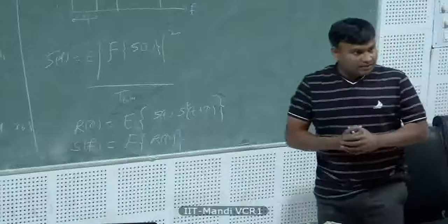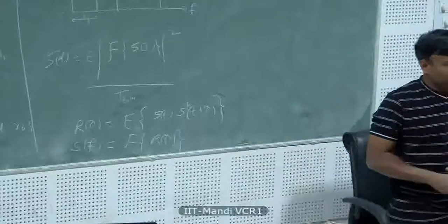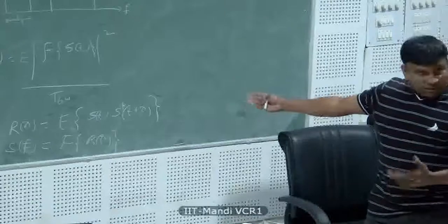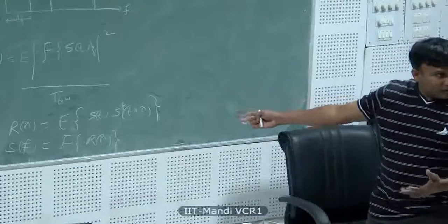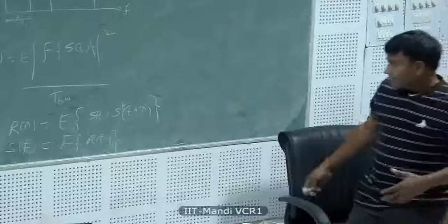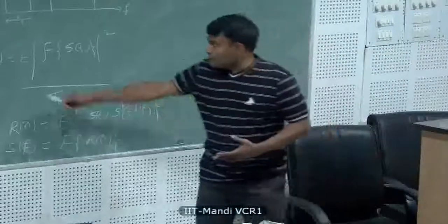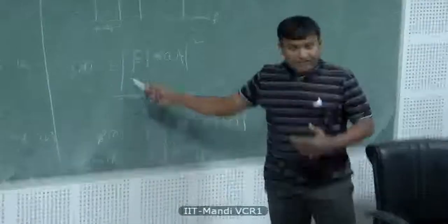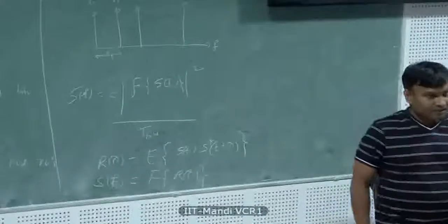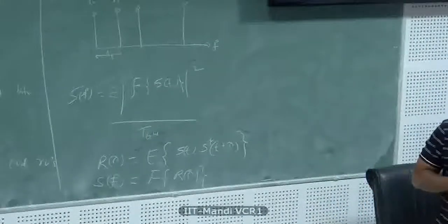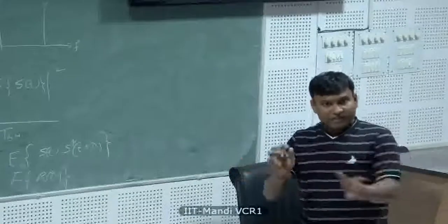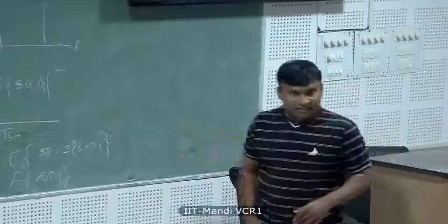When you deal with random signals, if you want to calculate the spectra of a random signal, you take the autocorrelation function, and then you take the Fourier transform of it. You'll get it. This is one way of doing this, and you can calculate spectra in another way by taking slices of the signal, take the Fourier transform, square them, and then average many such slices and divide by the total time taken.